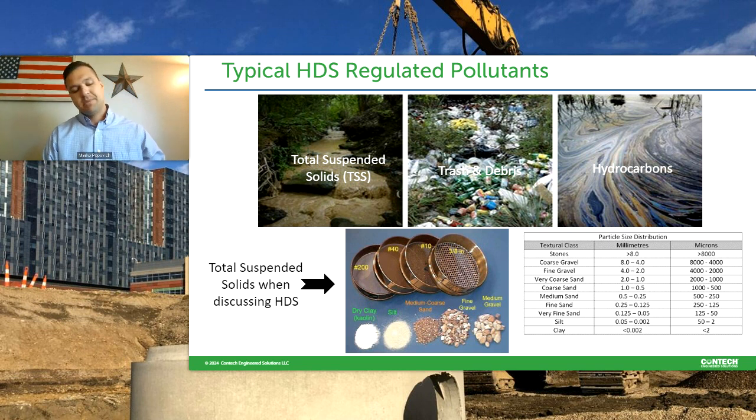Well, clays wouldn't be 50 micron, but 50 micron would be the small end for a hydrodynamic separator, and then 250 micron would be the coarse higher end for hydrodynamic separators. Again, anything finer, that's really when we would get into a more filter-based application. And then obviously, as you would just imagine, the larger particles are much easier to remove with a separator than those fine ones. Again, trying to set the tone for some basics as to what these separators actually do and the limitations around those.